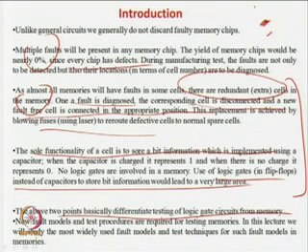This leads to a different kind of fault model, and it also means you have to go for repair and have some redundant parts so that repairing is possible. Repair facility is required because almost all chips have some faults. You have to repair it, otherwise your yield will be less than 1% or even less. Your memory architecture is very symmetric, and many things can be stacked up in one place, and the functionality is nothing but storing a 0 or a 1 and retrieving it back. So these two points make the philosophy of circuit testing different from memory testing.